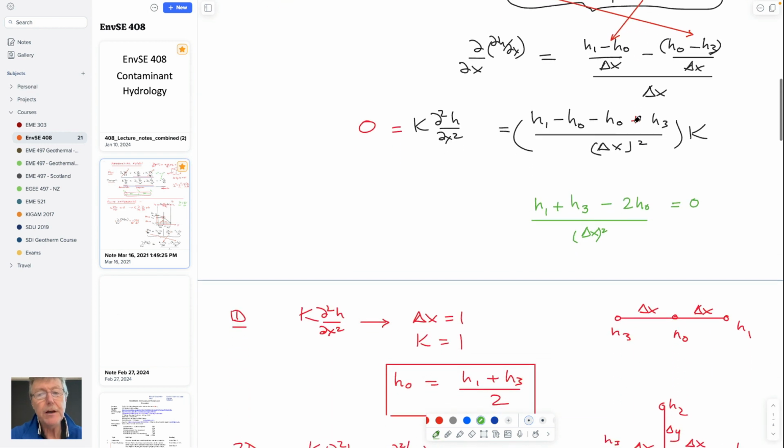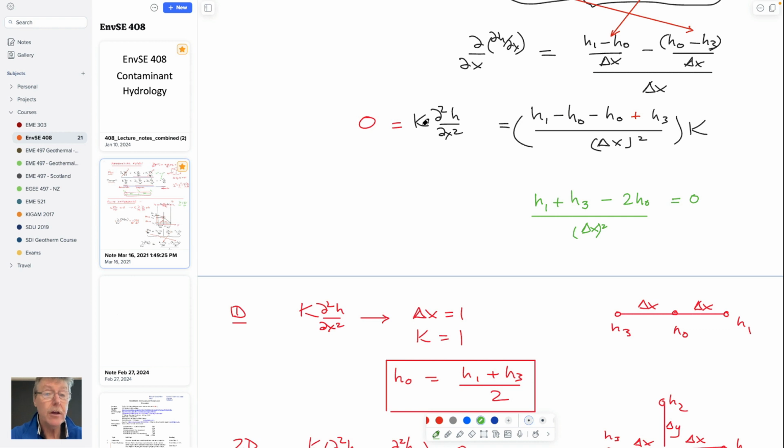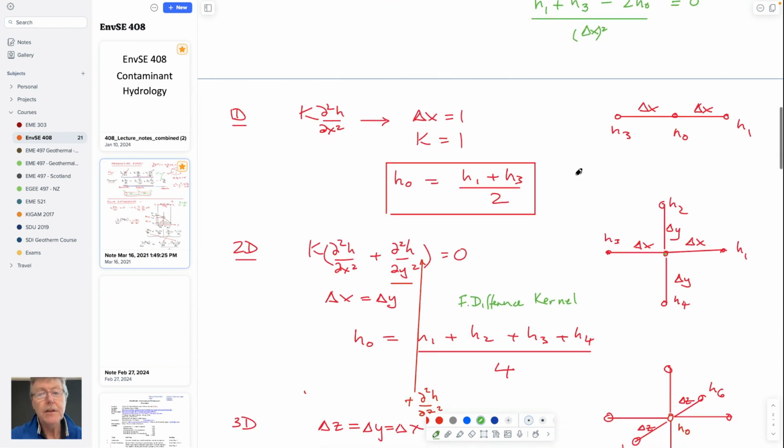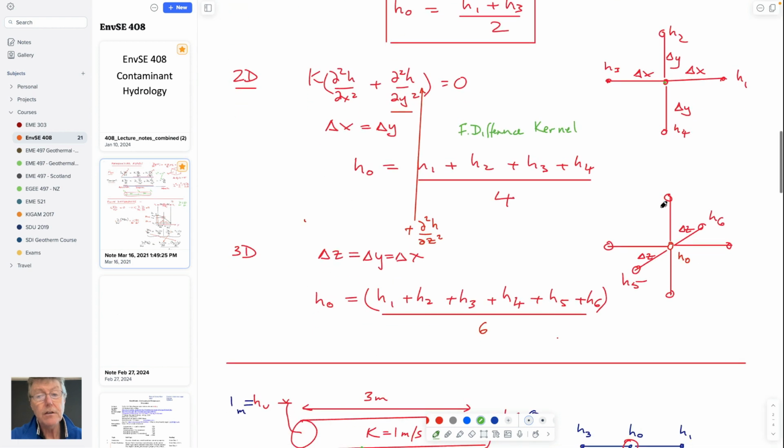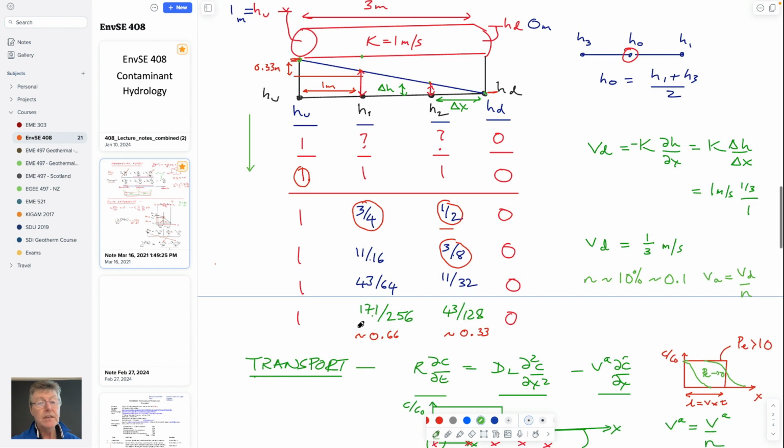It turns out to be a very simple expression if you take constant values of hydraulic conductivity and throw away the storage term. And the physical representation of those is that if you take the middle node, that head should just be the average of the upstream and downstream nodes. If you work in 2 dimensions, the middle node should just be the average of all the nodes around it. And if you work in 3 dimensions, it should be the average, again, of all the nodes around it. So these so-called residual methods, they're residual because you merely modify the value of this previous head by marching your way through the grid multiple times, as we just did here in 1 dimension, until you have a solution that doesn't change between the iterations. That gives you the correct distribution of heads.